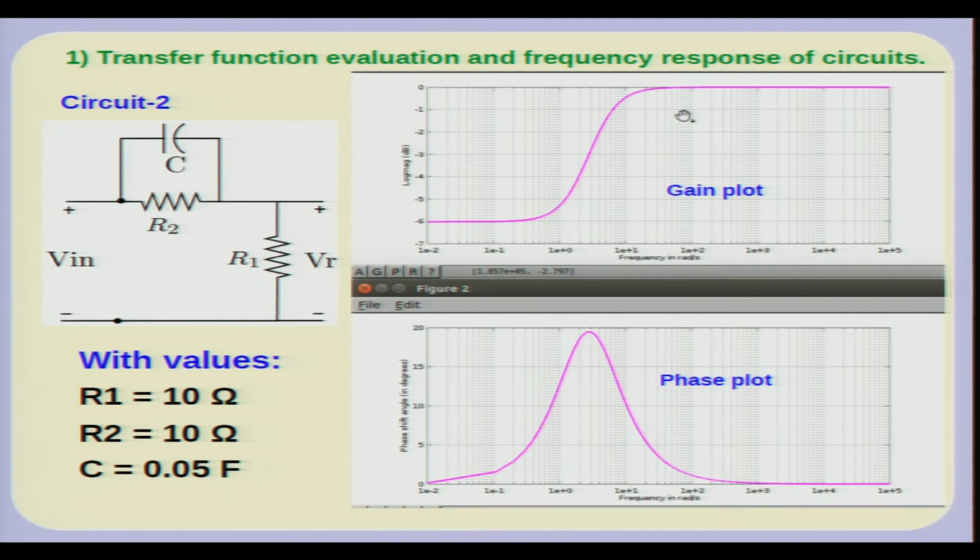So, that is an important thing, that if you load it very little, this is the transfer function, but the transfer function may get altered in case you load it. Similarly, this filter when connected to some other part of the circuit may load that circuit. If it is just the source, then it is loading the source. Sometimes of course, the source also has a source impedance, so that also alters the overall transfer function which you may get.